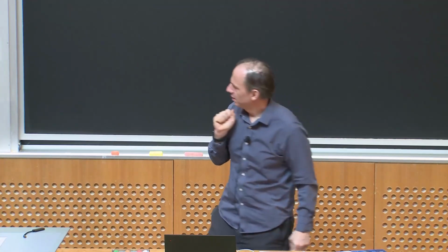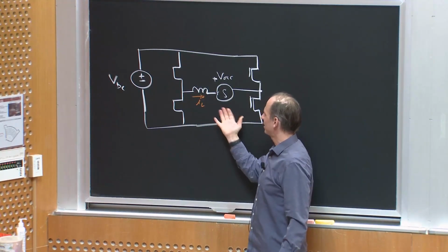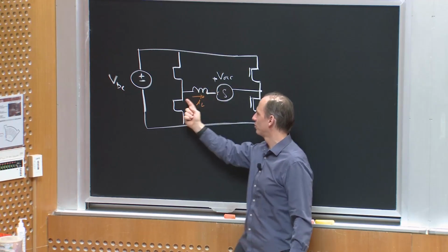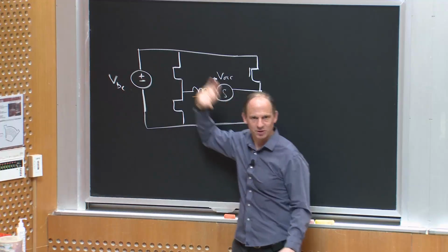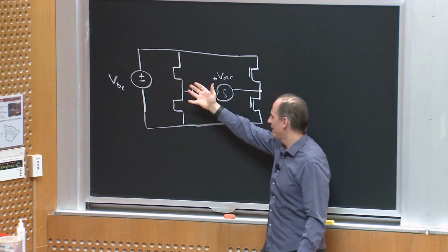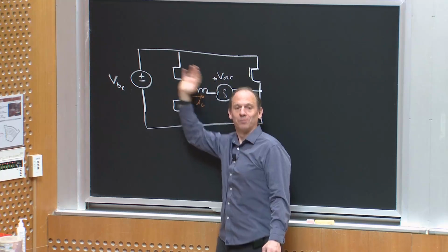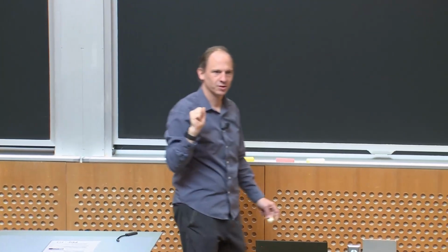And in fact, if I think about it, from AC to DC this is very much like a pair of back-to-back boost converters, right? It's taking energy from here, boosting up to a higher DC output voltage. So just like we talked about early in the lecture, I can think of this as either a buck inverter or a boost rectifier. Any questions about that?